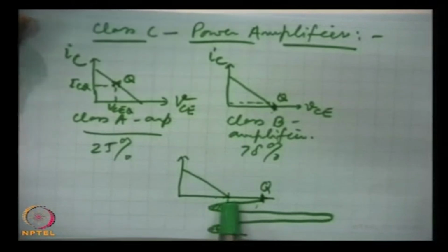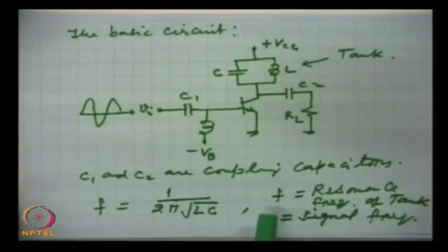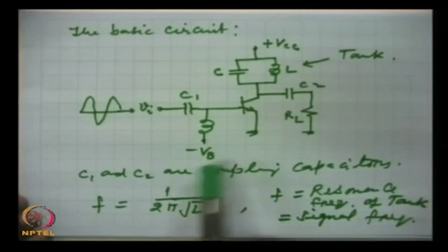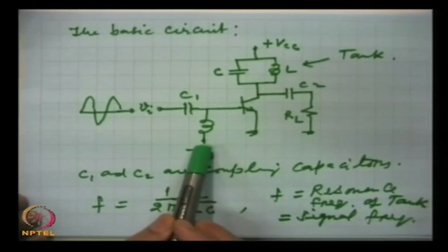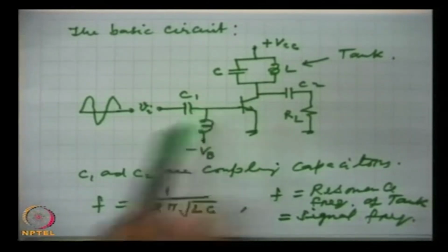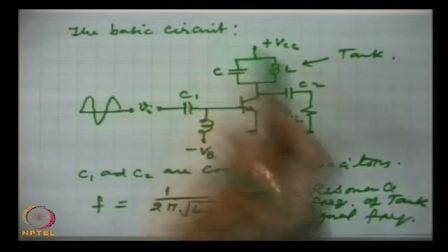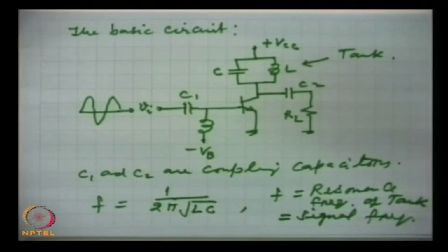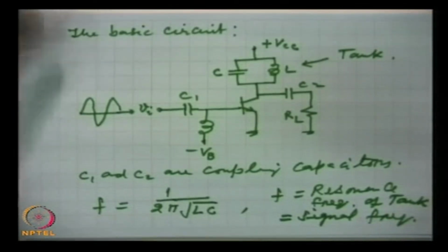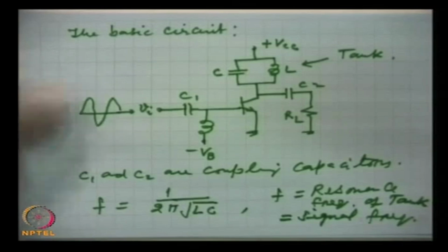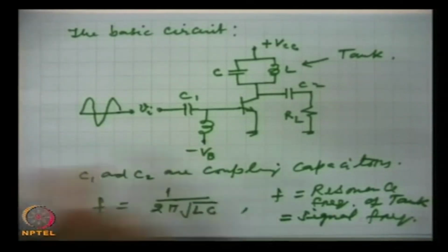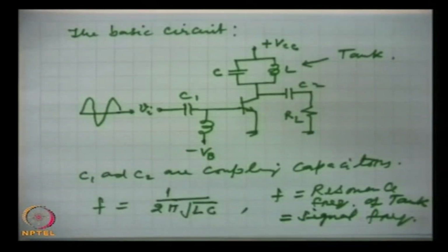It is so negative, and that negative bias is provided through this inductance from here. By a DC source, a negative voltage is applied, depending on the power for which we are designing the circuit and what input pulse will be available, and according to that we choose the negative bias.